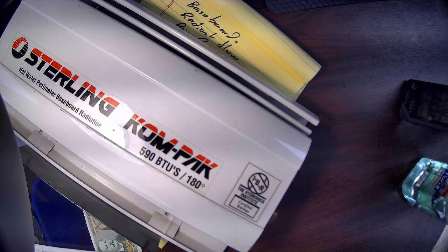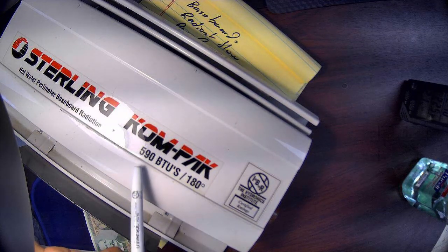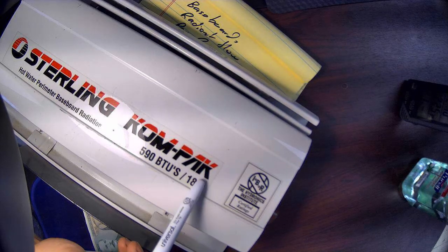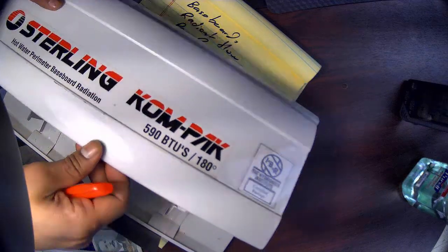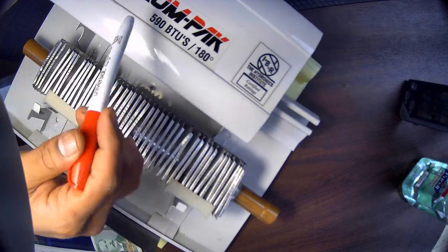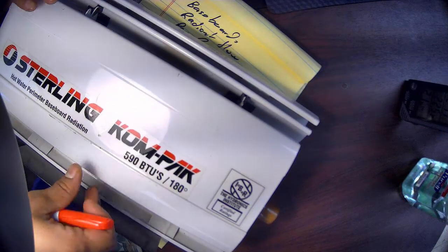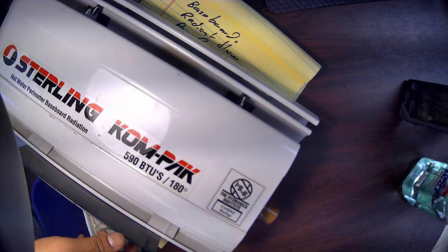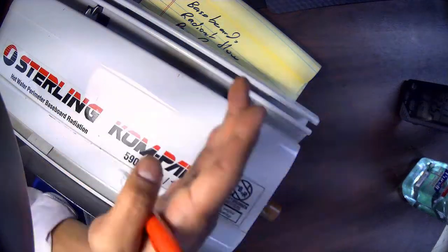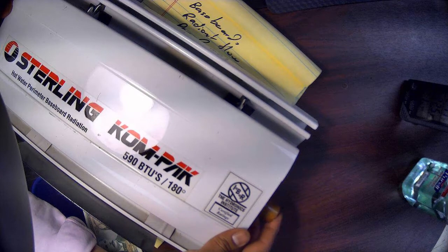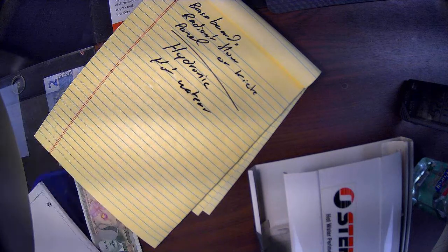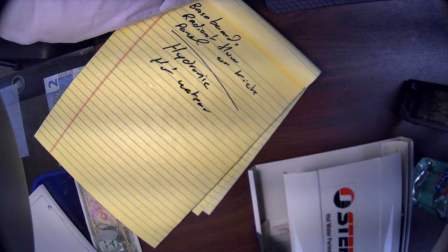And this one says here, this is the information we need to actually register: 590 BTUs per hour at 180 degrees. That's the temperature of the water that you would like to have circulating in these tubes. So 180, and based on that, it will give you 590 BTUs per hour. So this is going to be the radiation, and that's actually per foot. This is almost a foot. I'll say it's more than a foot, but for this piece, it's going to be 590 per hour. So I'm going to put this aside here and have you think about that a little bit, and I will change my camera again to the way it was.